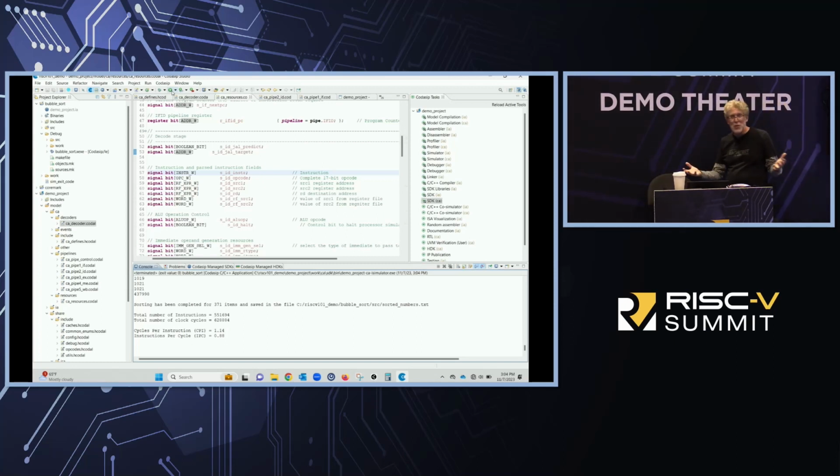So I've just shown you how you can take a look through the profiler and learn several different things: how I can reduce the total number of instructions by collapsing 2 into 1, and how to modify your microcode to reduce your CPI. Those are the two numerators in your equation, so your application is going to higher performance.